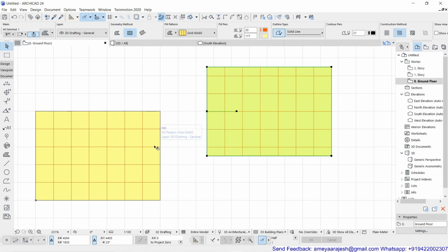It is not going to make any difference even if I copy this pattern somewhere else, the link to field origin will always be on, and it will not be calculated from the project origin. I'm going to show you one more interesting thing, but please try the option which I have explained until now, and then try this one also.